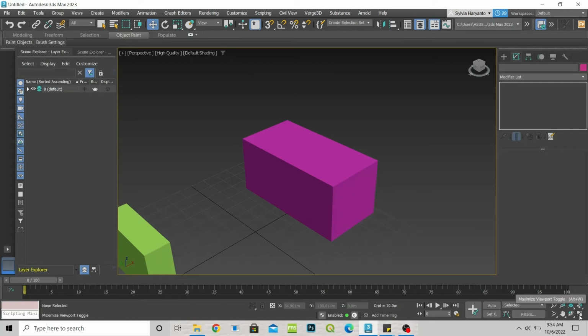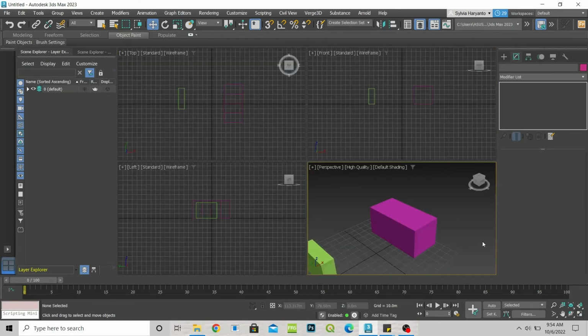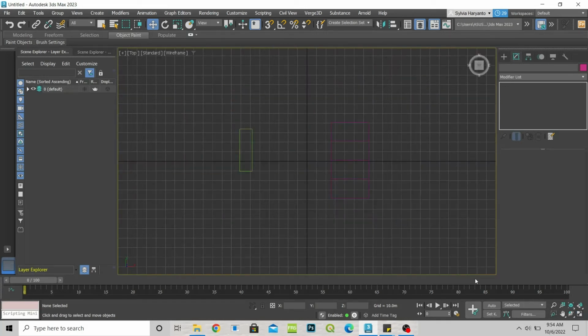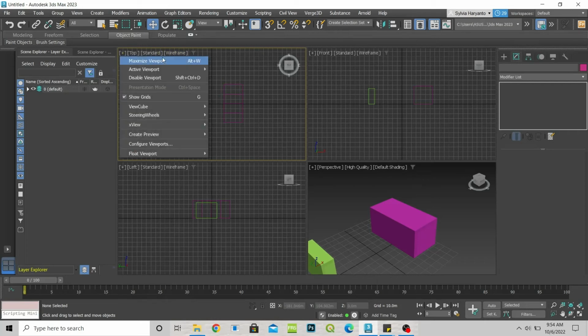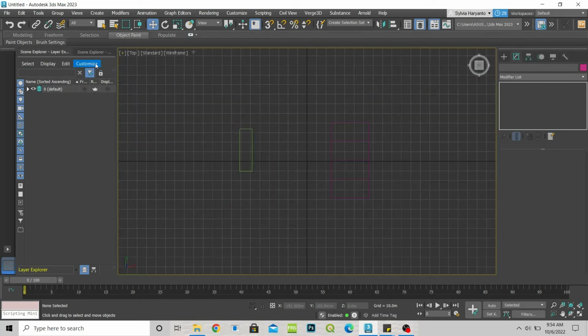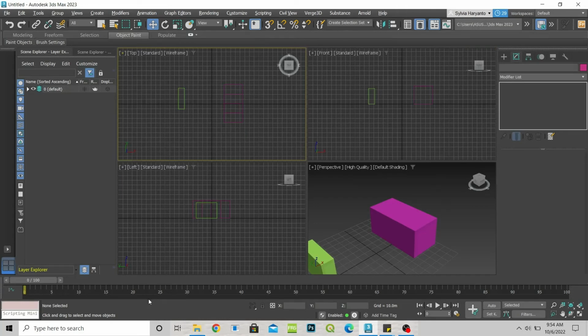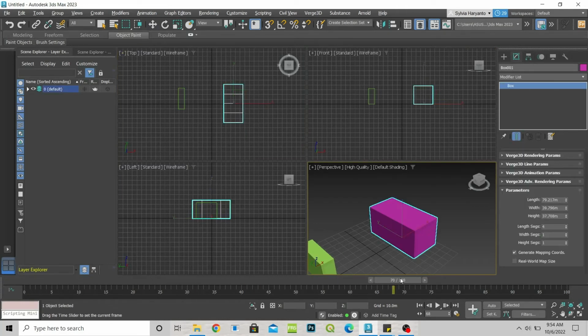As you can see in this bottom right corner, this is a maximize and minimize tool. So if you select one of the viewports and you want to see that view in a bigger picture, you can maximize and then minimize, or otherwise you can press this plus button and click this, or you can see there is a shortcut that has been assigned here, which is Alt W. This is what we call the timeline, and what it basically does is for animation, and these are the buttons to play and pause, next frame, and go to start or previous frame.